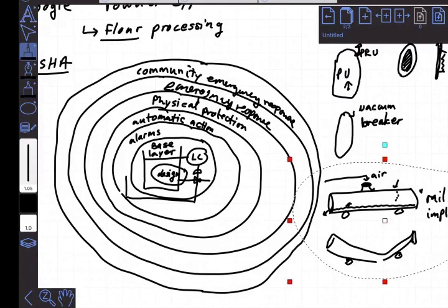And the rest of Chapter 9 details a whole lot of different ways in which we can design these things. So what exactly is a safety instrumentation system? What are the things that are different about normal base layer control, the interlock system, and alarms? How do we design alarms in a rational way so that we don't overload personnel?